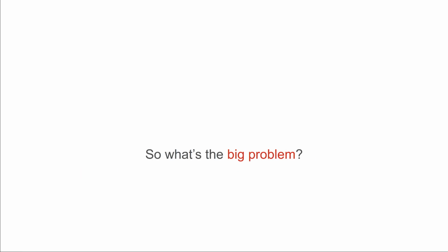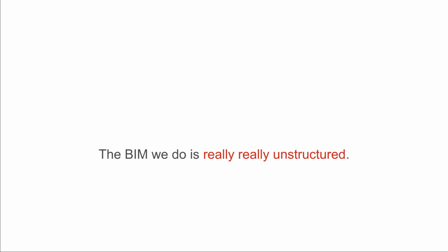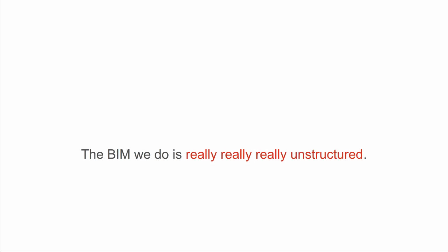Traditional BIM authoring tools like Revit and ArchiCAD don't use open data standards. So the data that Revit uses to describe walls is different from ArchiCAD and so on. And this means that we can't transfer walls very easily from one software to another. But more importantly, it means that the quality of our data just does not exist. There are so many ways to describe something as fundamental as a wall, never mind more complex things, and we're too busy fighting over whose wall description is the best instead of focusing on more important things.